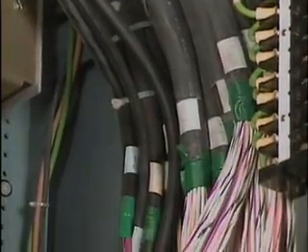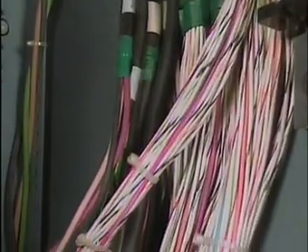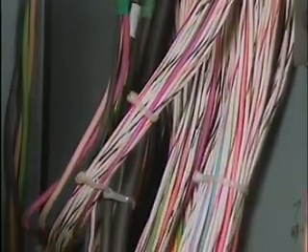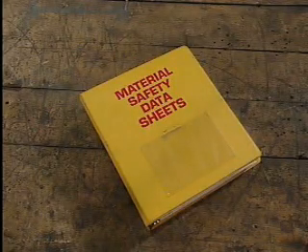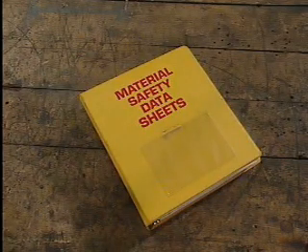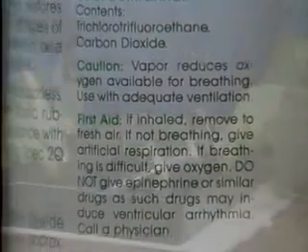There's one more important consideration to remember whenever solvents are used. Some solvents can chemically damage electrical insulation. This may result in injuries or equipment damage caused by short circuits, grounded circuits, and even fires. Whenever possible, it's best to use an approved solvent that is non-flammable and non-toxic. If you're unfamiliar with the solvent, be sure to check the solvent's Material Safety Data Sheet, or MSDS, and the solvent's container labels for important safety information.